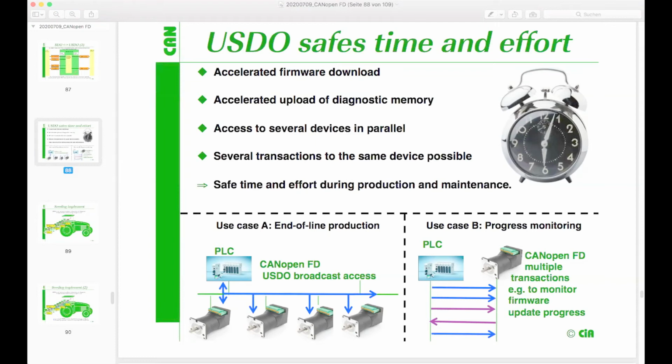I don't have to consider anymore the CAN identifier. The CAN identifier uniqueness is already solved by specification, and several devices dynamically, just when it's needed, can access or place a request to a specific CANopen device. So this allows dynamic cross-communication all over the network.